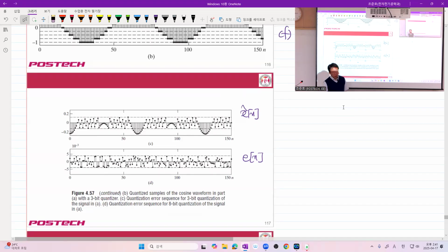But what they wanted to do is that, anyway, we usually implement second order based signal processing. I don't know if you understand what I mean, but when we handle random processes, if we want to have a linear system, then we usually only utilize the second order statistics, which means mean, autocorrelation, variance, not kurtosis or other higher order moments, just up to second order. So up to second order, what could be a good description?